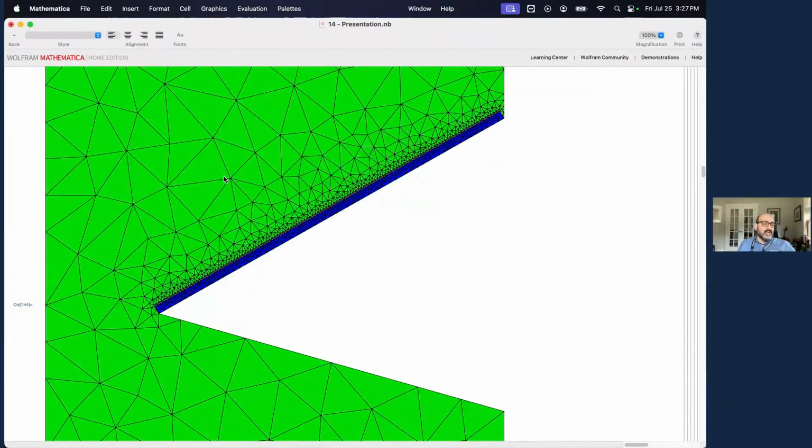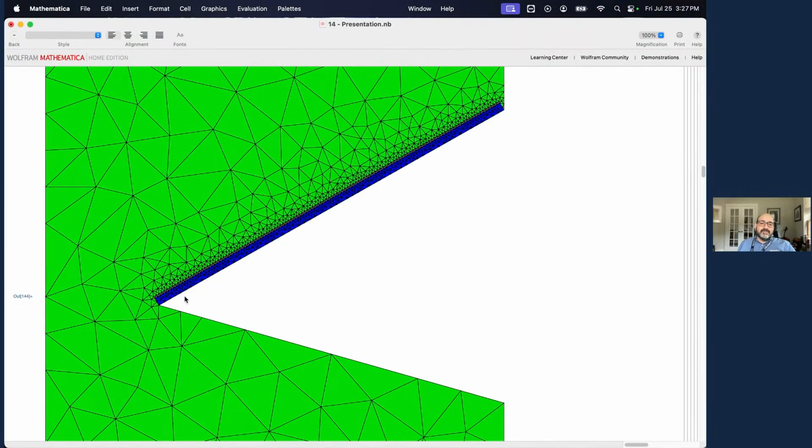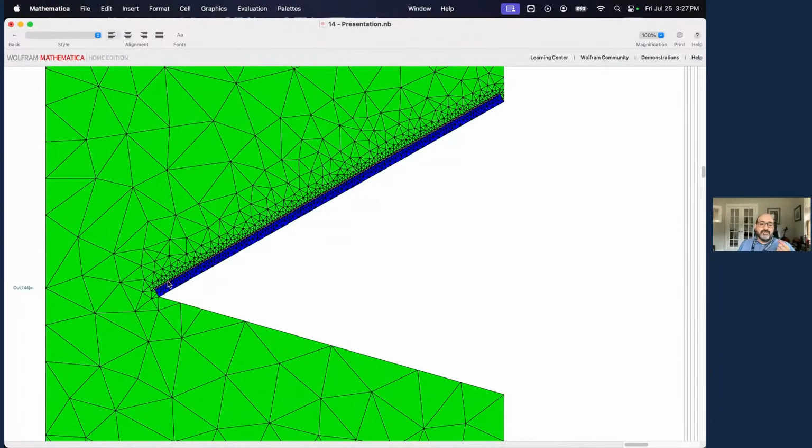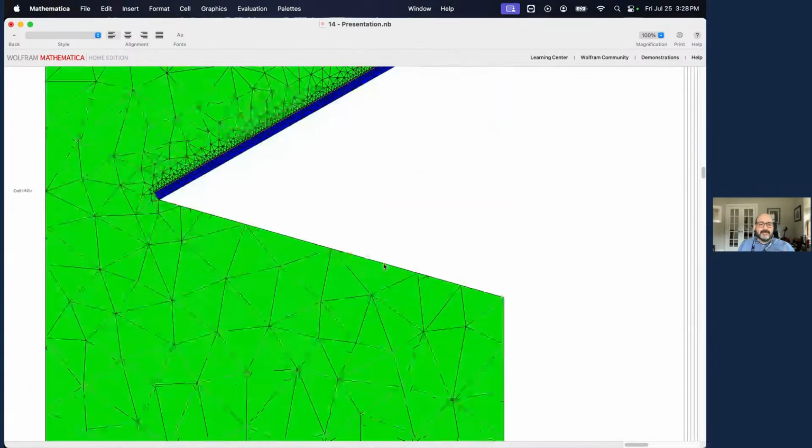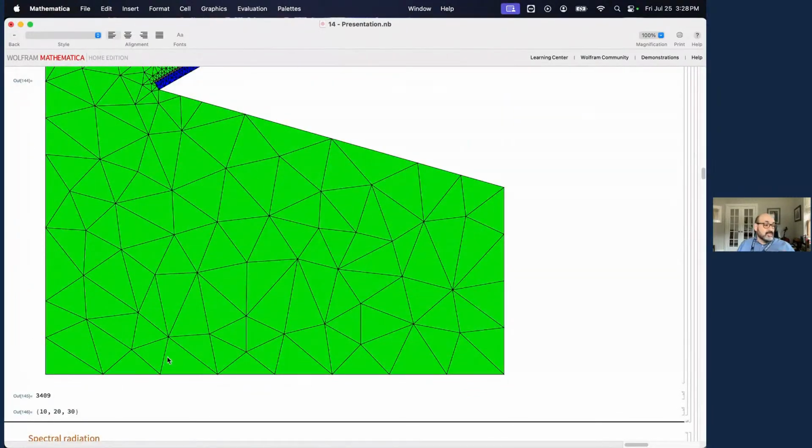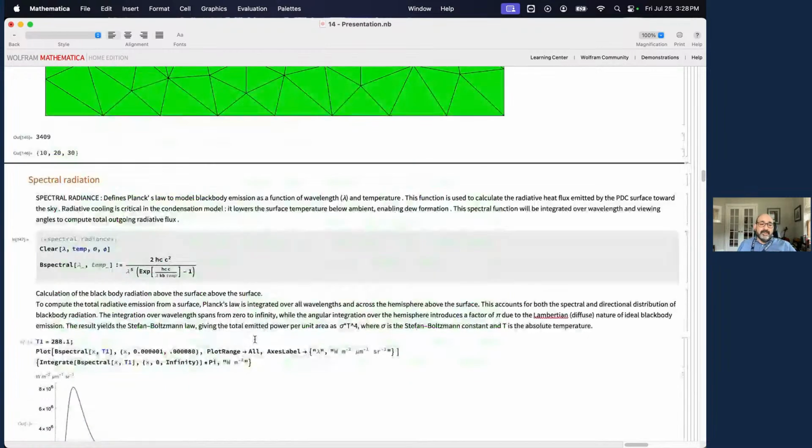Now look at what I did. Since I already have my Navier-Stokes solution, now I take another mesh and I inject the results into my new mesh. The results that I inject are only the most important ones that I care about. It's just the area next to the plate, right? And the plate itself. And that's where I get a better refinement. Now I went from 70,000 elements to only 3,000. This is very important because now you're reducing the solution time very significantly.